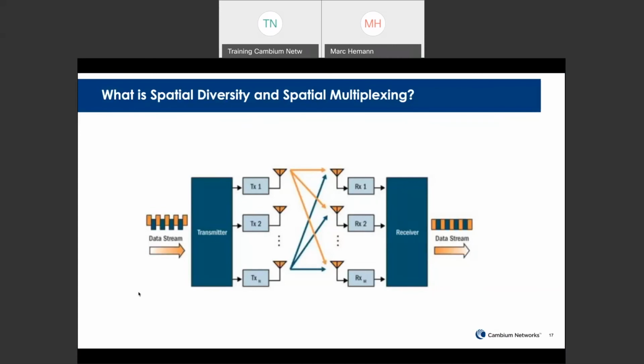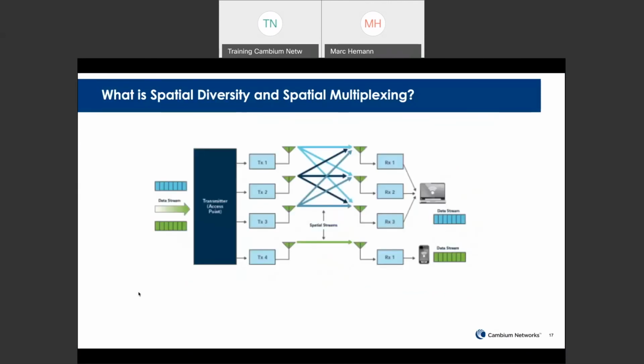And here's the great part. Each unique spatial stream can contain data that is different from all the other streams transmitted by a different radio chain. What we're doing is splitting a signal into multiple parts and then sending each new part through a separate radio chain. So now the signal goes out in 2 or 3 or 4 parts instead of 1. To add to this goodness, each spatial stream will take a different data path because there's a very slight time difference between the transmitting antennas. The fact that the multiple streams will take different paths due to the timing difference is called spatial diversity. This process is often referred to as spatial multiplexing.